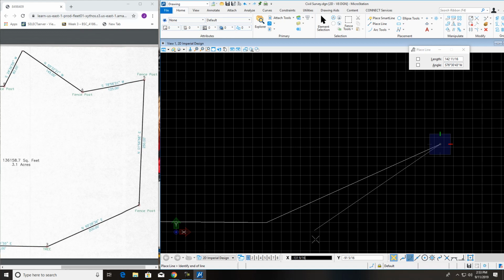So right here in this tab, I'm going to write that in as northeast, and it's going at a 250-foot clip. 250 foot, tab over, A for angle, and I'm just going to back out of all that, 1, comma, and looks to me like it's 01, semicolon, puts a degree on there, 56 minutes and 58 seconds.